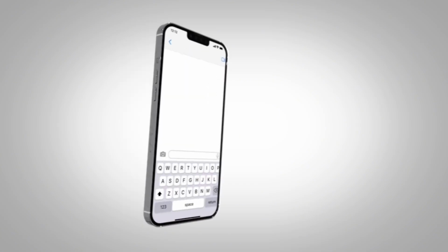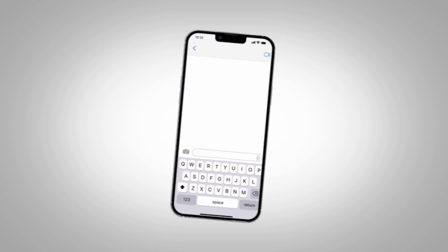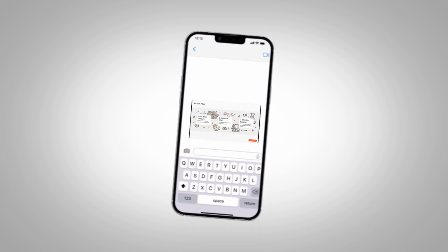First, try increasing the back pressure. That's going to force a much more intense blend. Second, optimize your screw speed, your RPM, to get a nice uniform melt. And third, if you want ultimate precision, use a gravimetric feeder. See, dosing by weight instead of volume is just way more accurate and consistent.